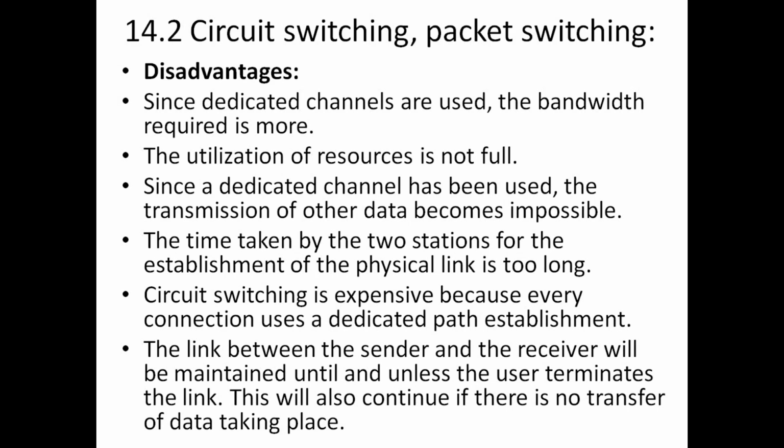Overall bandwidth requirement is more because you have to fix it. Now, even if you're sending a lower limit of bits, you still have to utilize that much bandwidth. The utilization of resources is not full. You don't completely utilize all the resources. Some of them are always wasted. Since a dedicated channel is created or used, the transmission of other data becomes impossible. Like if you're sending data to terminal 6, nobody else can send data to terminal 6 as long as you are talking to it.